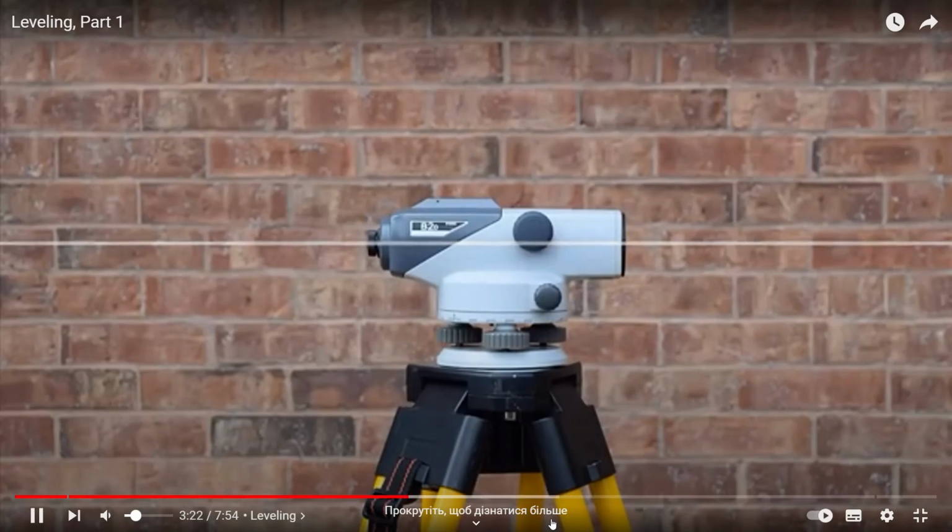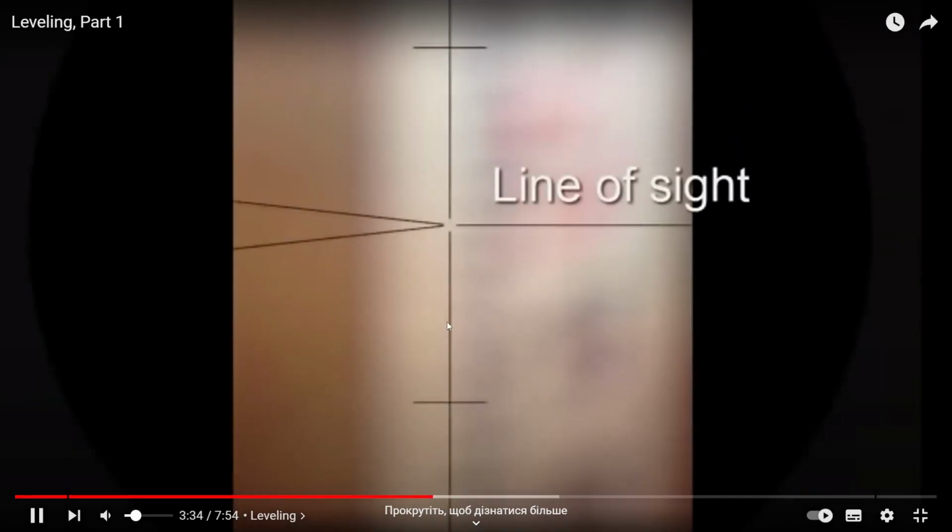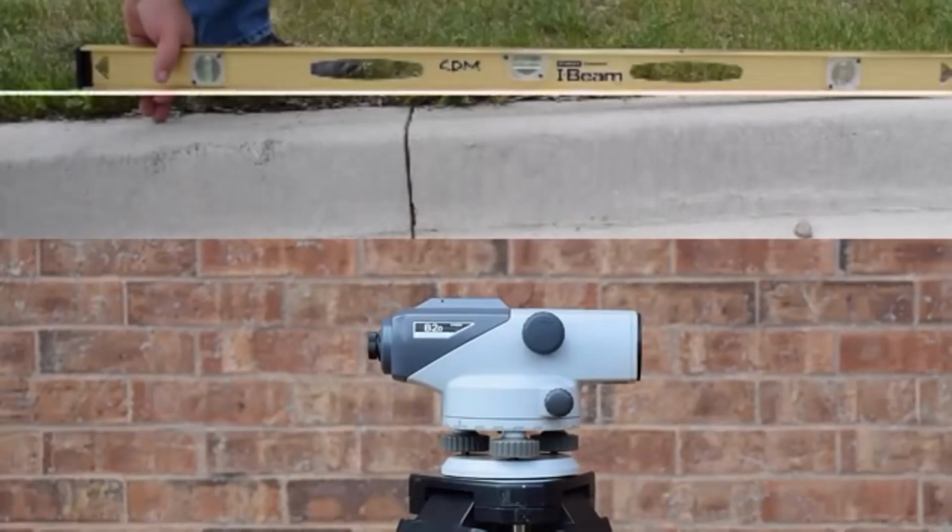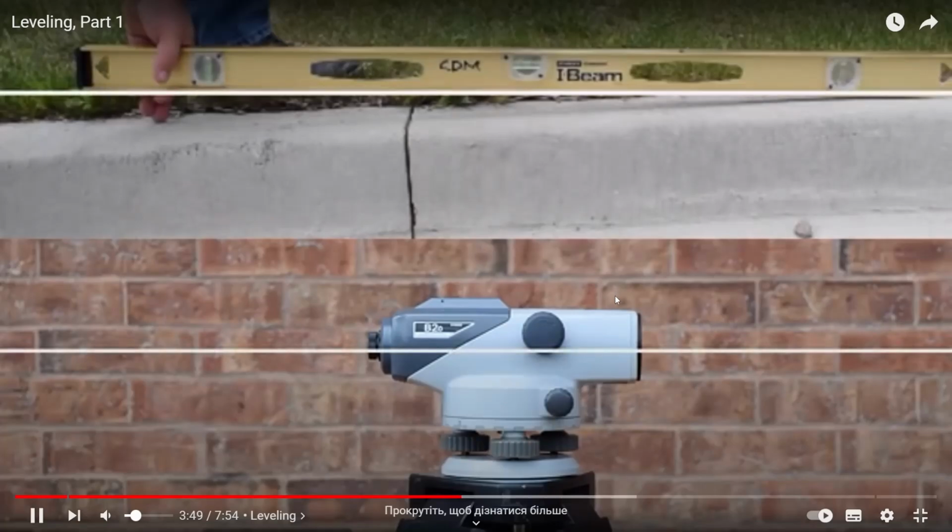The level telescope contains a crosshair. The horizontal crosshair defines a level plane in all directions. That is, your line of sight through the horizontal crosshair in the telescope diaphragm is a level line of sight perpendicular to gravity. Just like the underside of the carpenter level was held level just a few moments ago, now your line of sight is level.